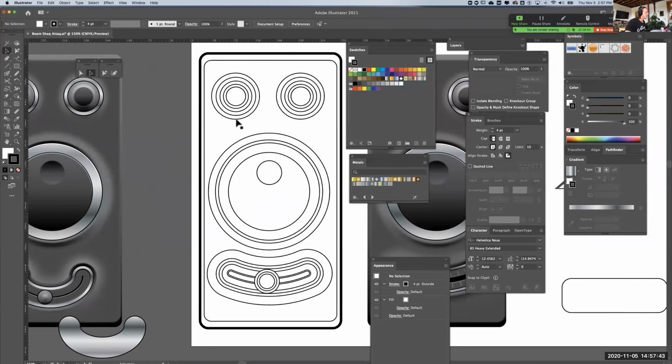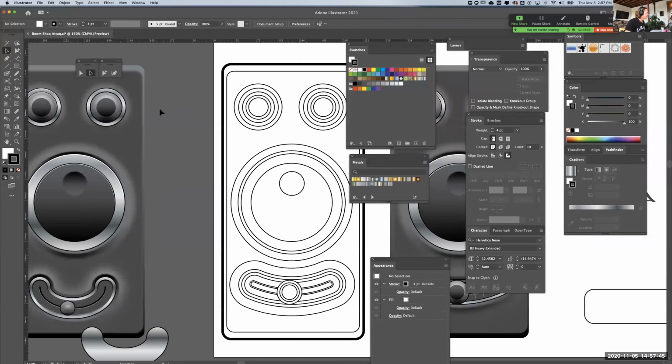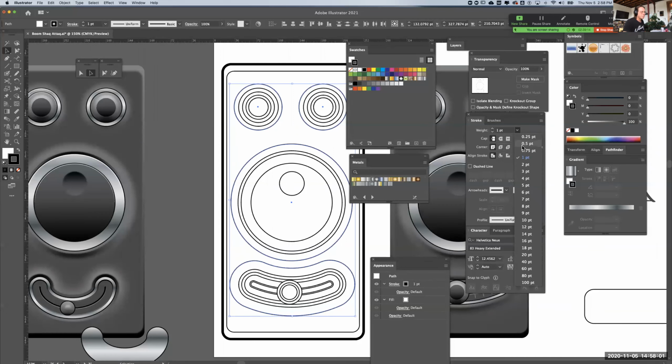These lines, as far as I can tell, I'm looking at this. This is a very soft line. You can see this is the soft line here. This is a very soft line. This is a soft line, and this is a soft line. And I want these lines to be super low power. So I'll go to 0.5. Down here, you can select 0.5. So we're starting to get some line weights.